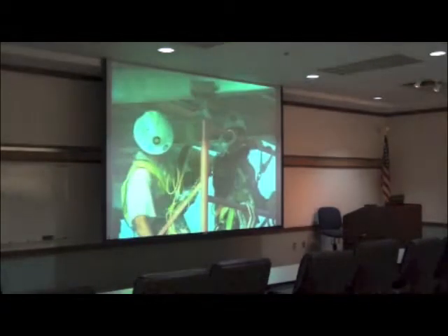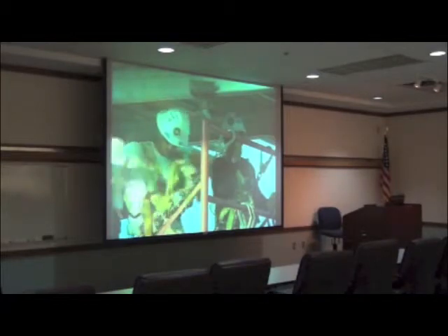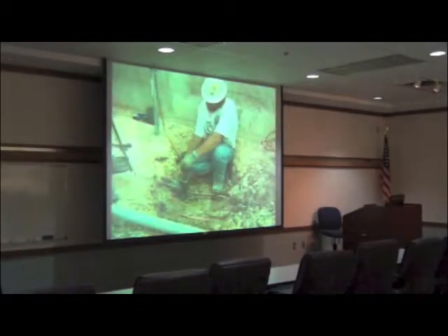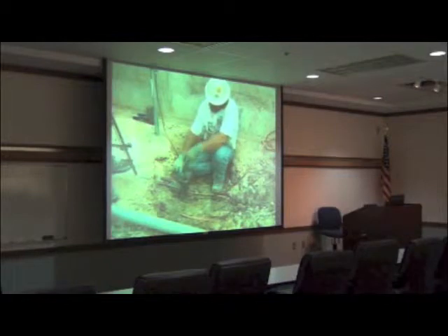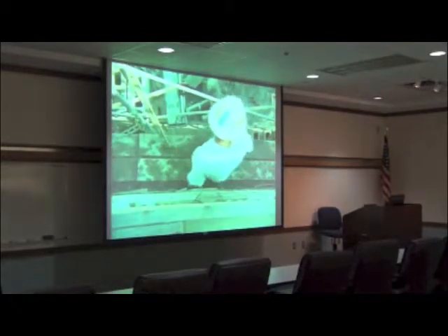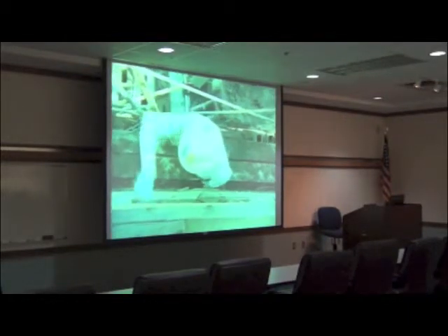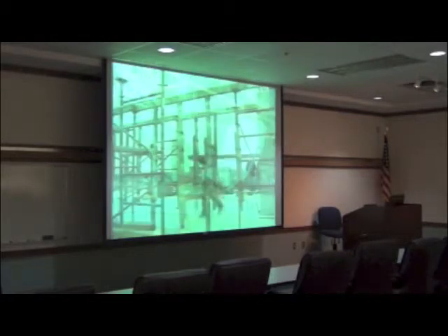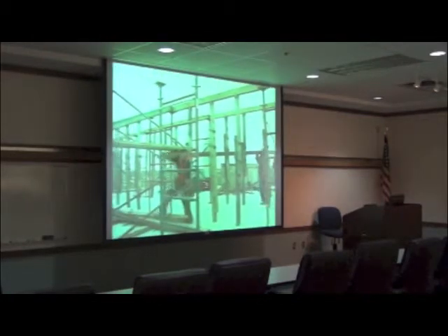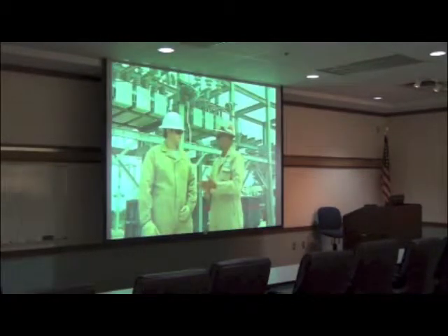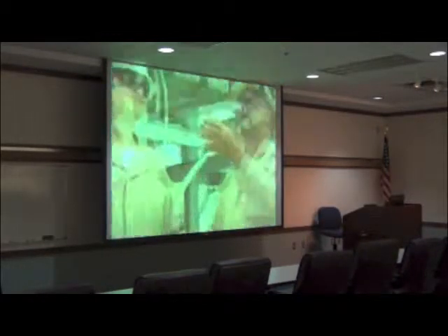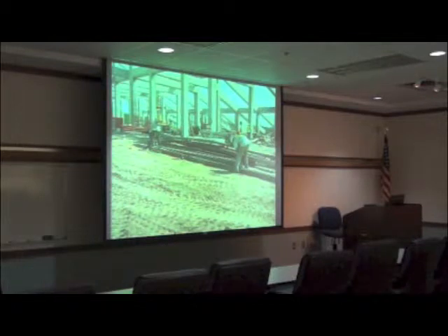Hard hats can protect workers from impact and penetration hazards, as well as electrical shock and burn hazards. Wear hard hats if you are exposed to risk of falling objects, bumping your head against fixed objects, such as exposed pipes or beams, or if there is a possibility of accidental head contact with electrical hazards. Be aware of special project or contract requirements that may require wearing hard hats at all times.